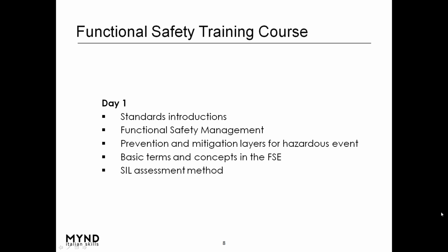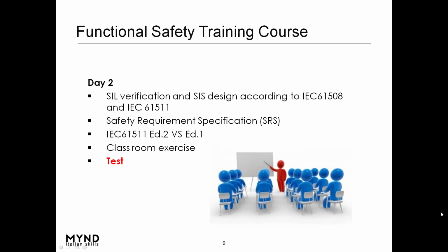The second day is mainly focused on the verification of the SIL and the design of the safety instrumented system according to the IEC 61508 and IEC 61511.